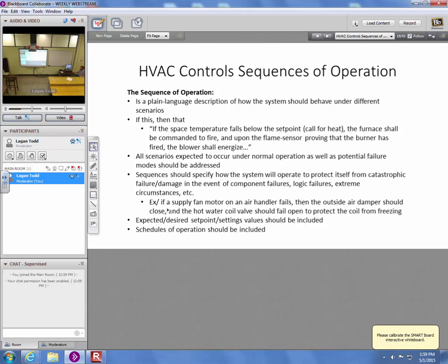Yeah. So a really good example of that is on boilers, especially these newer sealed combustion condensing boilers, where they have their combustion air ducted in, usually through a PVC pipe to the boiler, and then they've got their flue gas going out, and the flue gas now is not coming out at 400 degrees like it does in an old, less efficient non-condensing boiler. You can get frost. Usually you've got a bird screen over your flue at the top, and a bird screen over your combustion air intake, and I've seen both of those frost over.